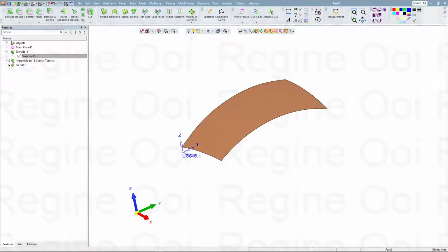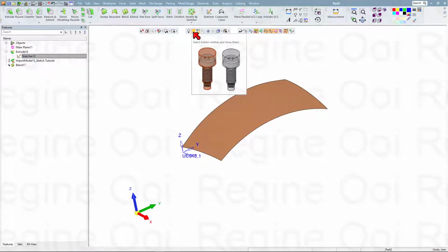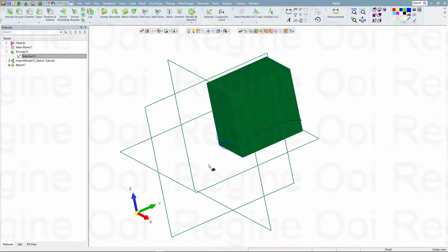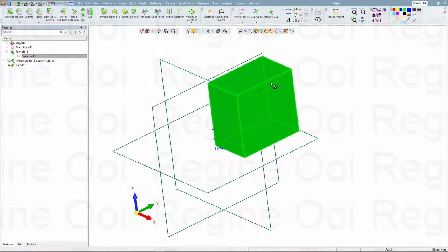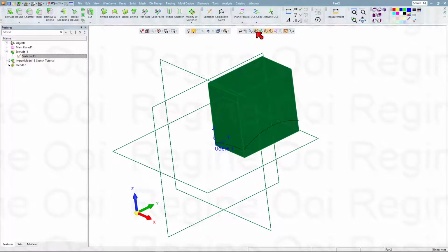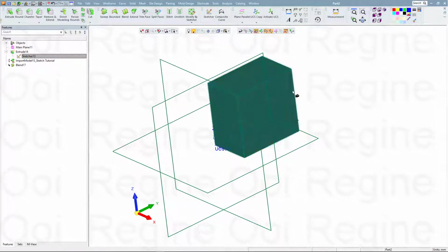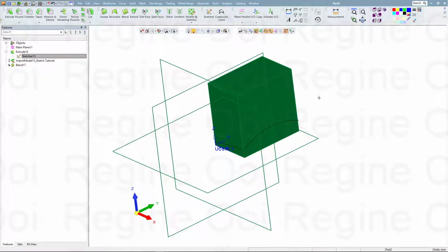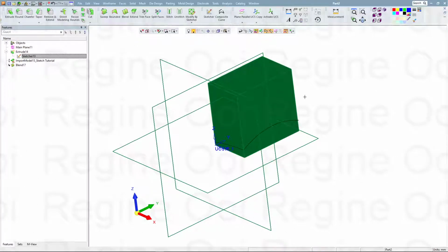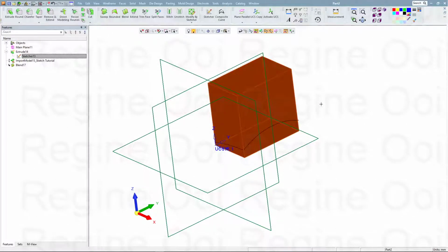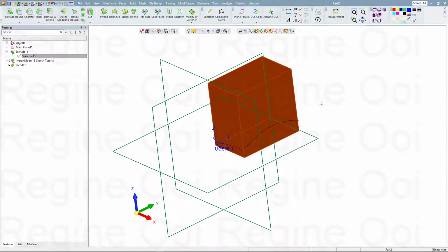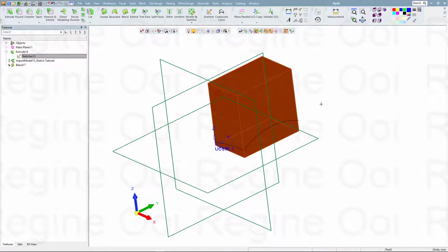Now I want to display the 3D model, the solid file. So I will click this show, so it will show all. So I select this model, make sure filter object is selected, select this model. Green color means it is in hidden mode. So I will select this to let the system know this is the object that I want to show out.